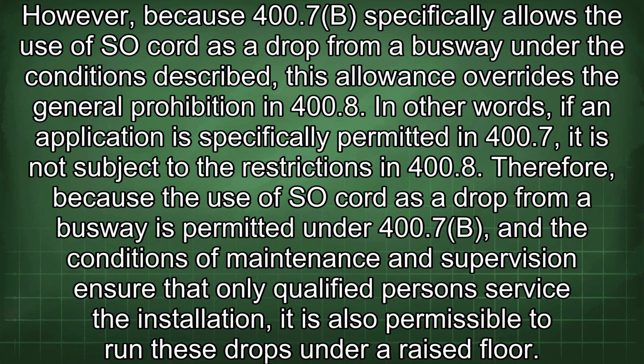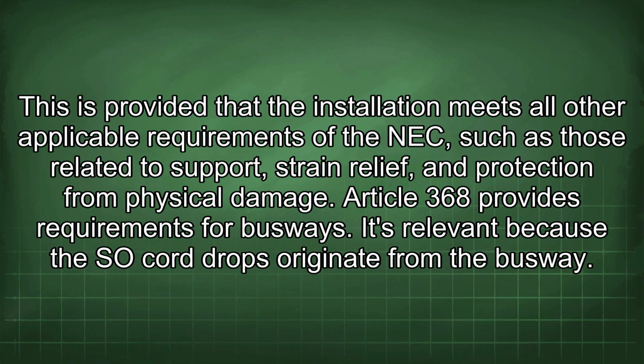In other words, if an application is specifically permitted in 400.7, it is not subject to the restrictions in 400.8. Therefore, because the use of so-called drops from a busway is permitted under 400.7(B), and the conditions of maintenance and supervision ensure that only qualified persons service the installation, it is also permissible to run these drops under a raised floor. This is provided that the installation meets all other applicable requirements of the NEC, such as those related to support, strain relief, and protection from physical damage.